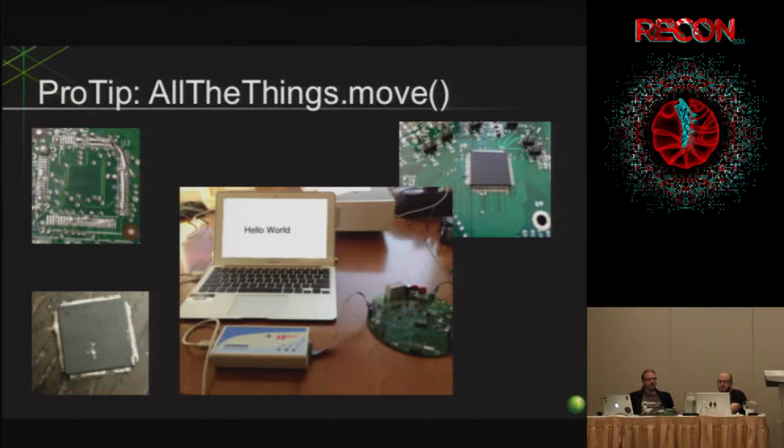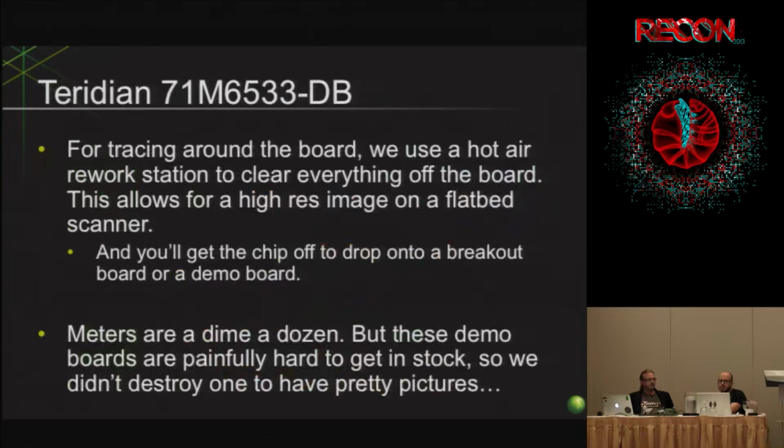I take Chip Quik to the actual meter and pull that chip off, then solder it back to the demo board, because the demo board's already broken out for debug, for ICE, for everything you would want to do, since they're typically using that for development. So I just reverse it and solder the live meter SoC onto it, at which point I can typically dump whatever I want. It's a really lazy man's trick, if you like to solder at all. And since you've already blown that chip off, you've now got a dead meter that you're never going to use, when you start playing with hardware again,